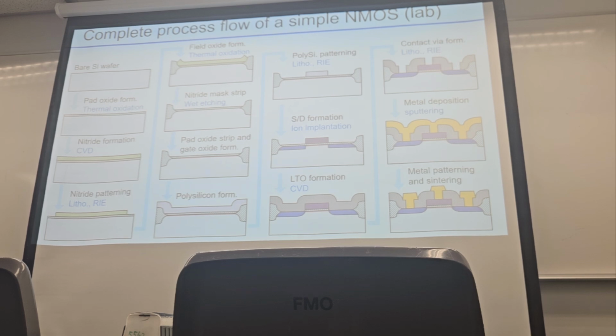You can refer to this one, which refers to the NMOS, okay? But the process is not as complex as NMOS. For example, in the first several steps, it's similar to the NMOS. You start from the bare silicon, and then you have the pad oxide formed.